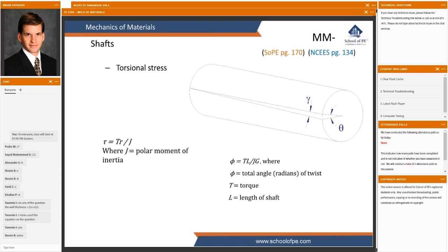The next way to put stress on something that we'll discuss is to put it under torsion. If we look at each tiny little element, a microscopic element of this, we might see that that little element is getting twisted to some degree. And of course, that angle of twist is gamma, where gamma is that interesting shear strain thing we looked at before that might have units, might not have units.